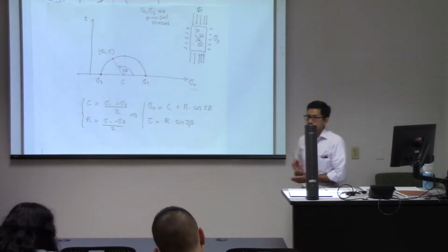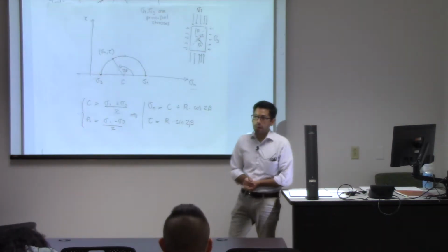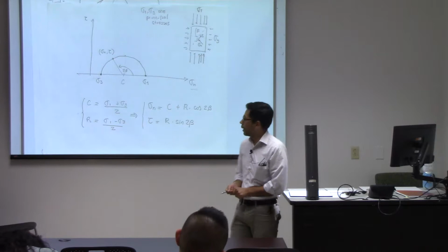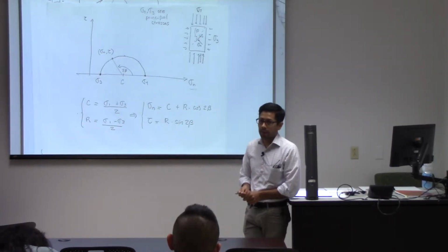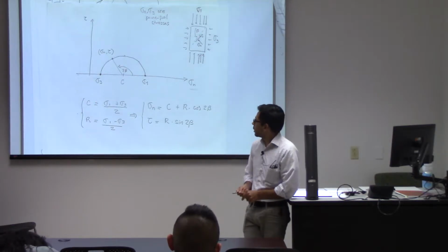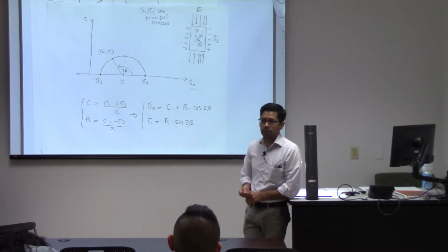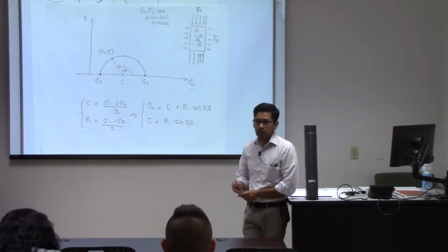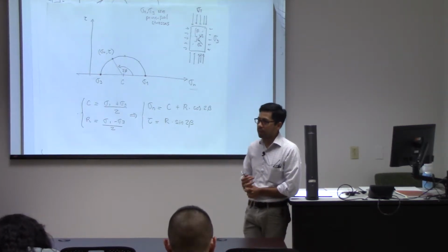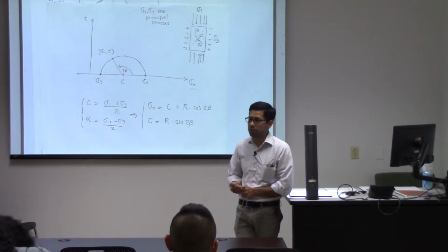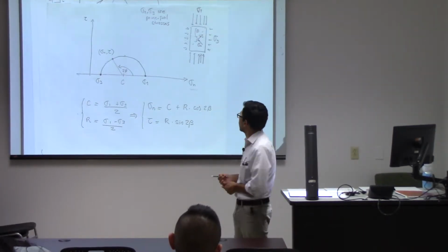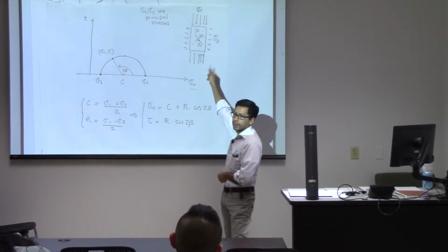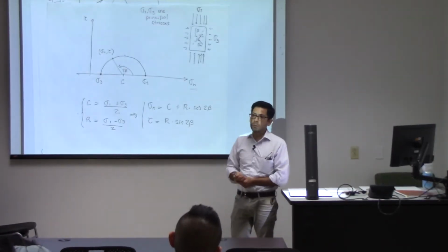This is super important for shear strength, because rocks, unlike materials like metal, do not fail due to the maximum shear stress. So now that we know the Mohr circle, what do you think is the plane with the maximum shear stress? At what orientation should I look in this rock to find the maximum shear stress?